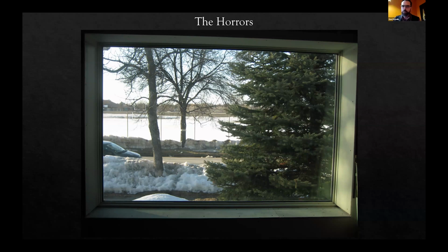But it creates a dead air space that fosters moisture production at the bottom of the window, even with decent windows, especially on a big north-facing window like this. It sees very little sun, and so if I had placed the window in the wall, it would have helped a little bit. It would have been in the insulation, helping increase the performance of the windows all around, not just this one.